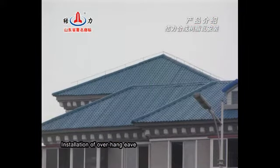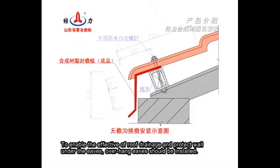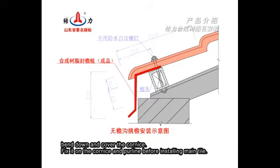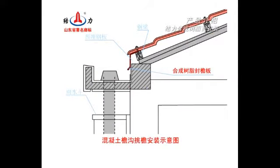Installation of overhang eave. To enable effective roof drainage and protect the wall under the eaves, overhang eaves should be installed. Metal and synthetic resin sheet are a better choice. Put in 100 mm from the eave edge. Bend down and cover the cornice. Fix it on the cornice and purlin before installing main tile.